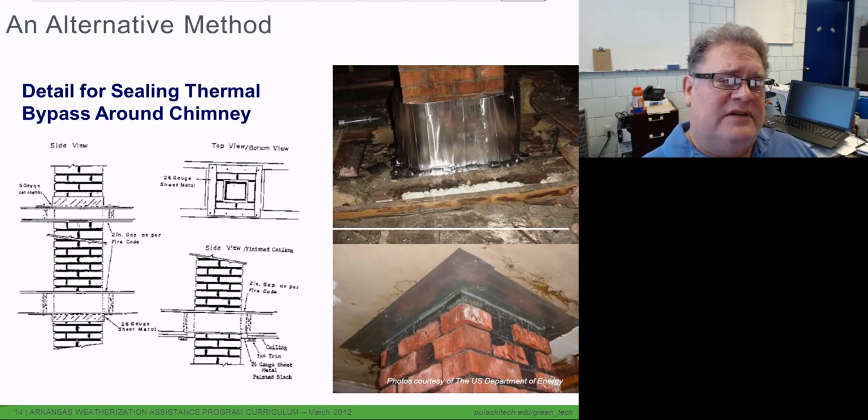So up top we have this metal with pre-formed folds in it. It's called Insul Shield. It's kind of nice because it has those pre-formed folds. It's easy to work back and forth, kind of like a paper clip, and you don't have to cut it. It's got these tabs on the bottom, nice to put screws in. So here they're creating the air barrier, or making their air seal, on the inside of the house.